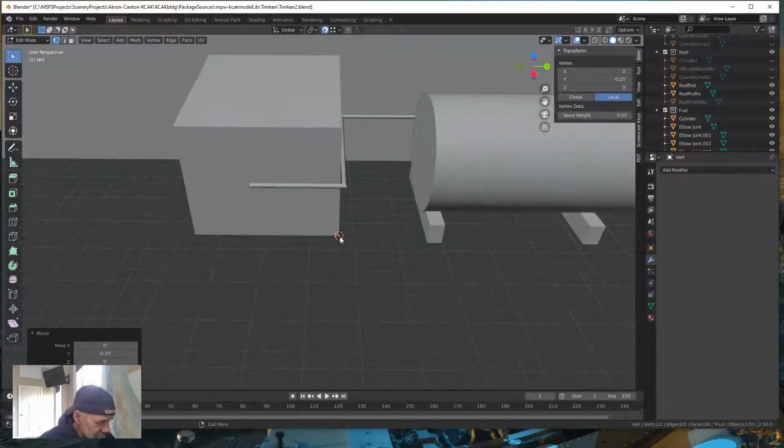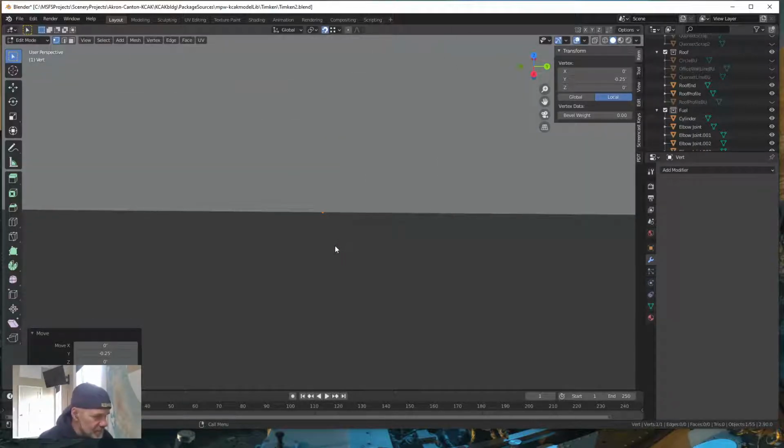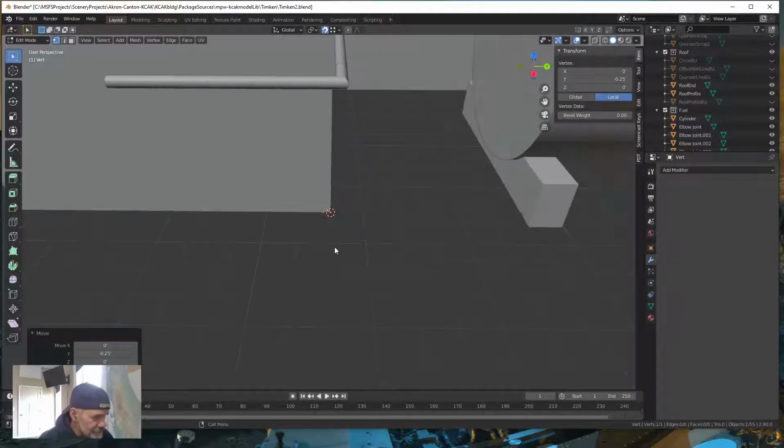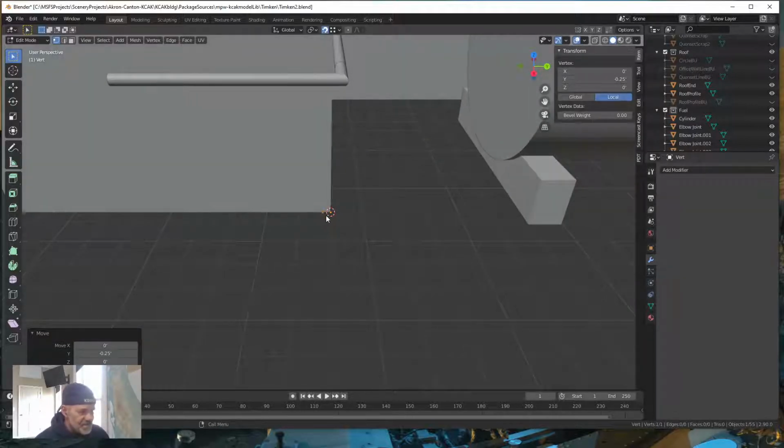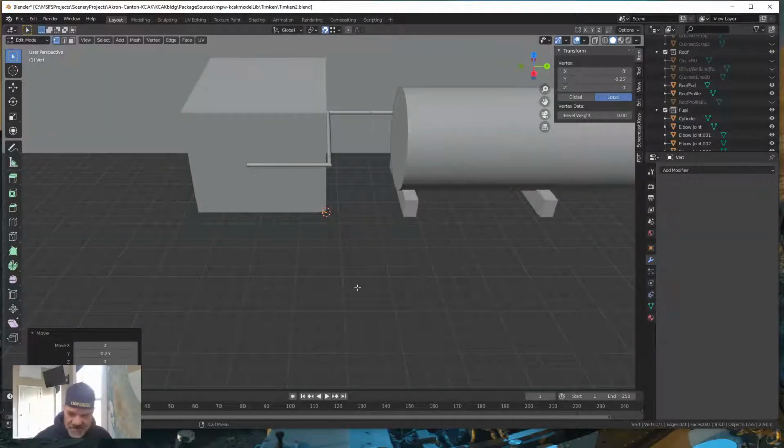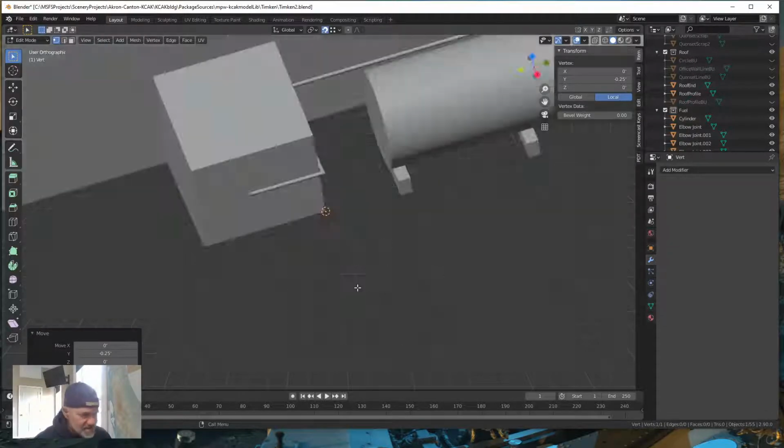Okay. This yellow dot is actually the origin, not the actual vertice. The vertice is right here. Let me hit P to focus. See, there's our vertice. Scroll wheel out. Now I offset this 3 inches for a reason, because we're going to make a line over this way, over to cross, and end at the end of our building. Then we're going to extrude those edges up 8 feet. And then we're going to apply a solidify modifier to it.